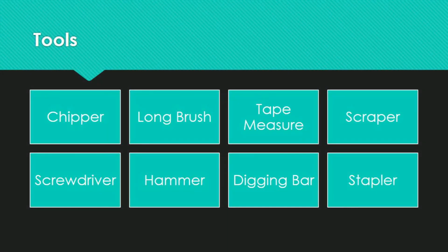The first is the chipper. So when is it being used? Well, after excavation, which we're going to talk about in a later video, a chipper is used to remove surface deterioration off the pole. Then another tool that you will use will be a long-handled brush. And what is it used for? It is actually used for applying preservative paste to a pole's below groundline shell.